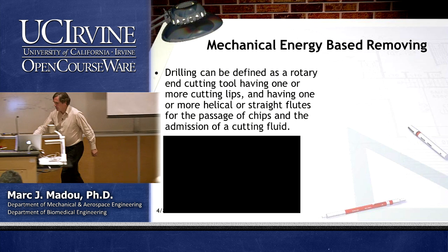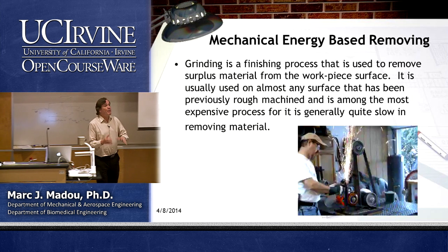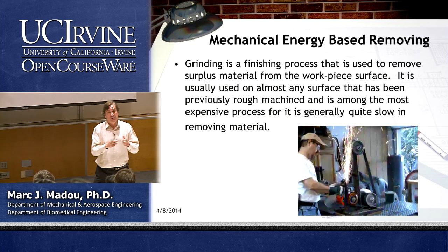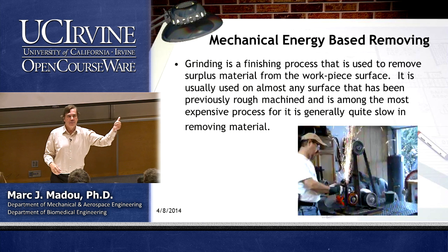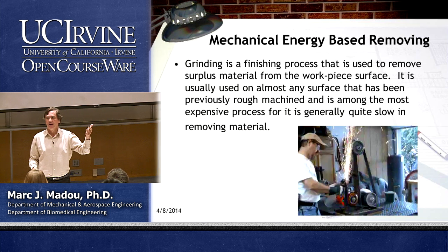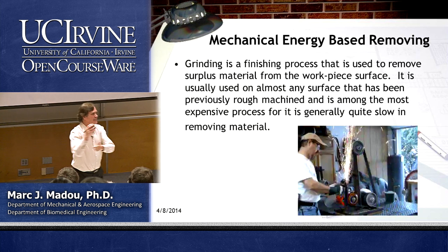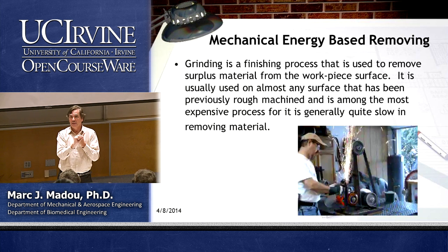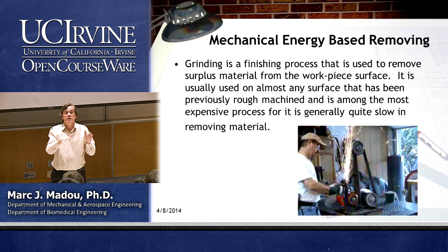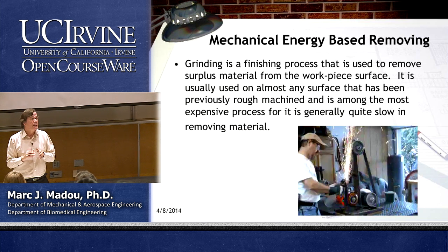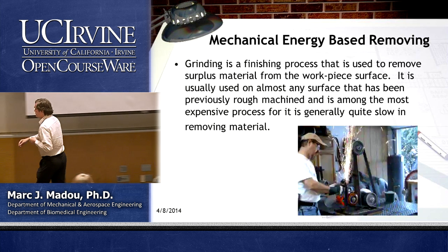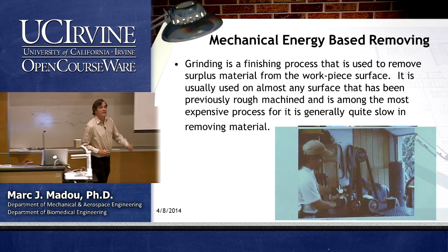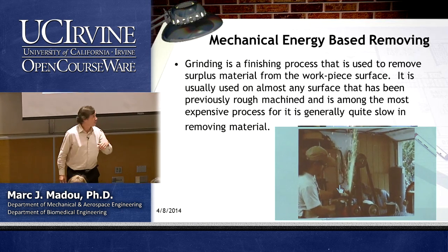Now, grinding was one that I hadn't shown you yet, but probably from what you saw so far, you could completely define what characterizes grinding. So in terms of energy domain, what we apply is obviously mechanical. Is it single point or multi-point? Multi-point. Will it be a more expensive or less expensive technique? More expensive, right? Because it's a primary, secondary, or tertiary technique? Tertiary, right? And we know the cost of a workpiece goes up the more you go to tertiary kind of machining techniques, right? One more thing. Is it subtractive or additive? That's a simple one. Subtractive, obviously, right?